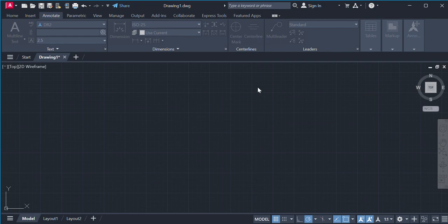Okay, and then next, just gonna have a look at the fits, see that everything looks right. It says if there isn't enough room to place both text and arrows inside your extension lines, the first thing to move outside the extension line, then you can choose whether it needs to start moving the text or the arrow, or both text and arrows, or whichever fits best.